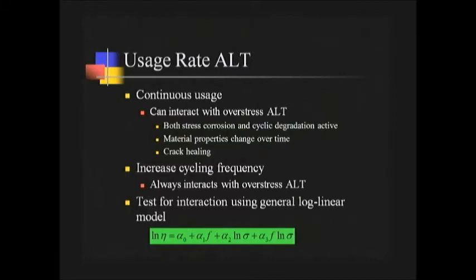And if we do non-stop testing, then we can end up driving the crack forward before the water can come in and change the material properties. And so we propagate the crack at a different rate than it would propagate at the same stress normally.